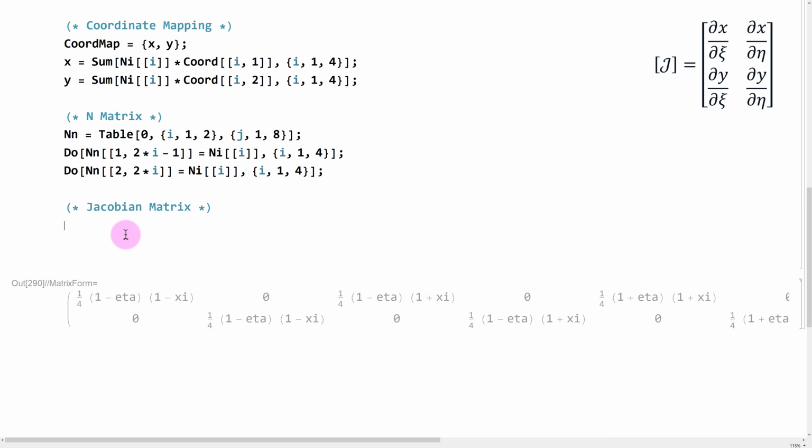Always. Now, this is a problem because if you think about our global system, our element cross-sectional area could be many different things. It could be 1, which is going to be smaller than our natural coordinate system. It could be 100, which is much larger. So what this Jacobian matrix does is it simply relates those two areas together, so that when we calculate our stiffness in our natural coordinate system, we multiply it by a factor which comes from this Jacobian matrix that accounts for the fact that in our global system, our element can be either much larger or much smaller.